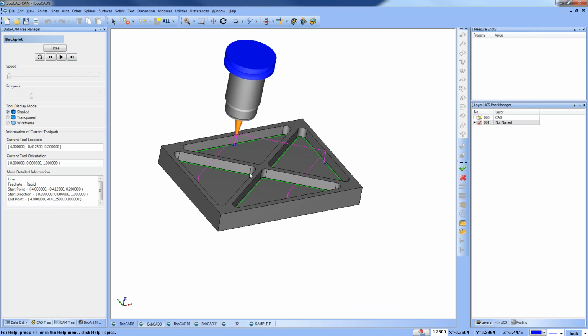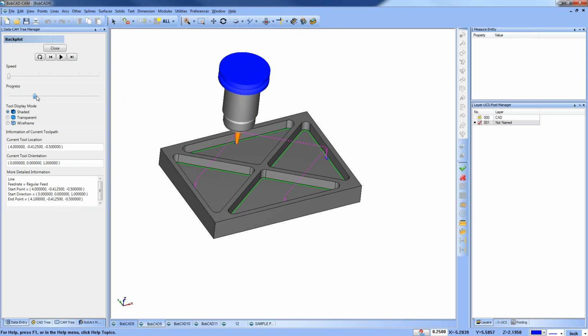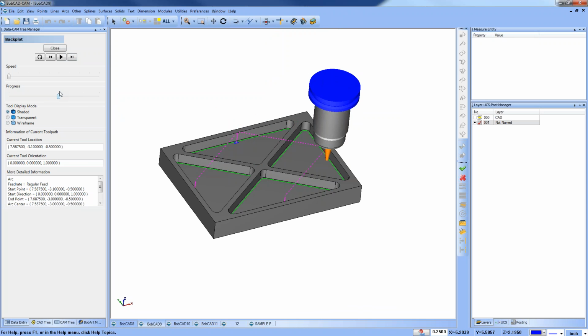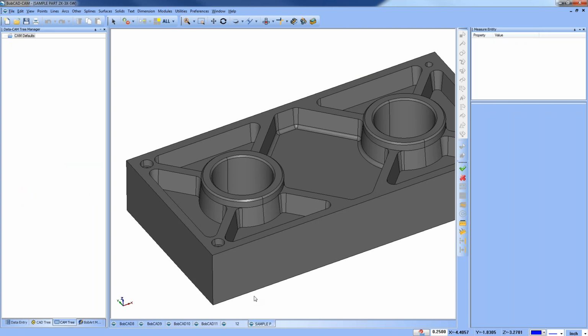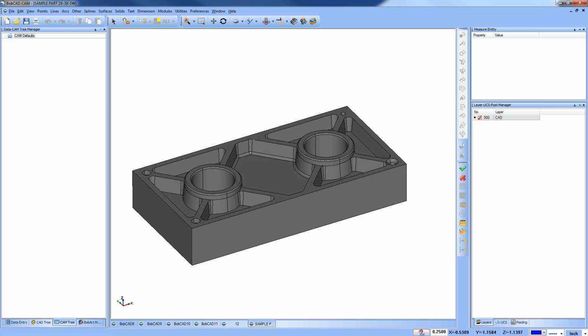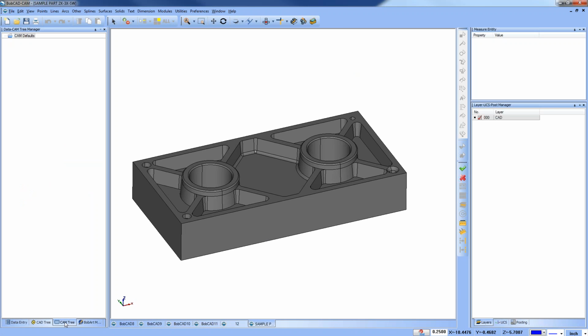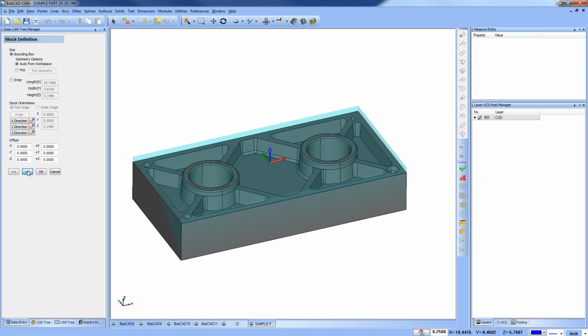Okay, so if you have a tapered wall pocket, a really easy way to do that is just to run a profile against the wall. There's a lot of different ways that you could do that, but that is a good way to do it. Now, you could also come in, like in this sample here, and say that you want to use a Z-level finish type routine. Z-level finish, you'd be using a ball mill.